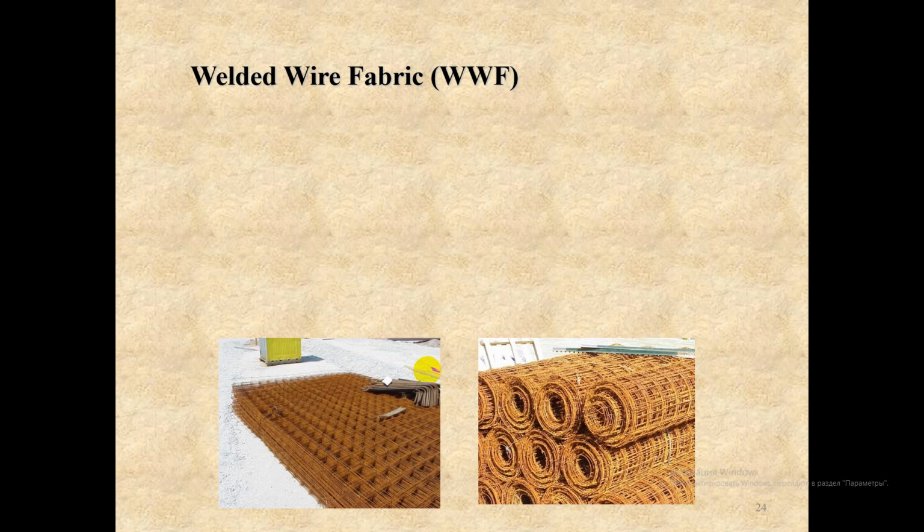The bent reinforcement should be fabricated into cages for columns and beams, and into mats for slabs and walls. Where the bars cross or intersect one another, they should be tied with soft iron wire, fixed with special wire clips, or tack welded to maintain their relative position.